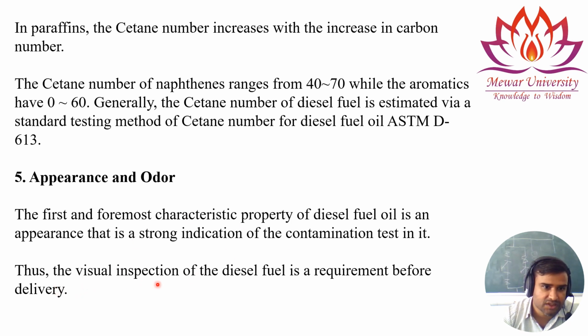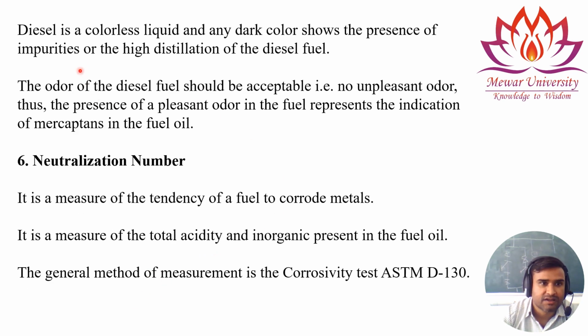So visual inspection of diesel fuel is required before delivery. Diesel is a colorless, transparent liquid, and any dark color shows the presence of impurity or high distillation of the diesel fuel. The odor of the diesel fuel should be acceptable, with no unpleasant odor.